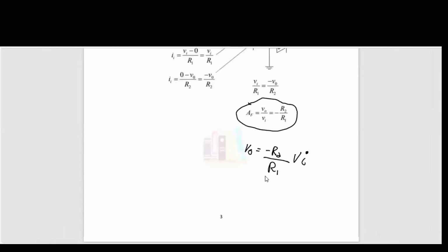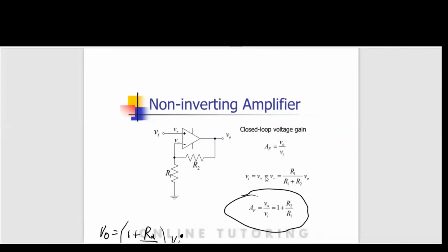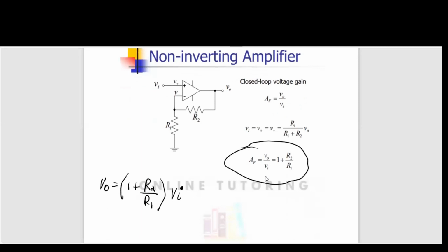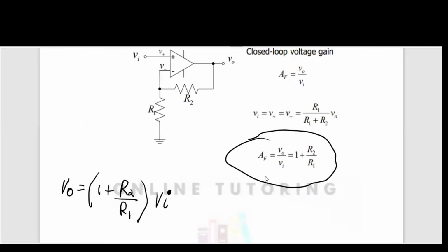Alright, so we're just going through. This one is literally just to sit down and remember the circuit. Alright, non-inverting amplifier. This should be familiar from physics. The equation for it is here, so you'll use this one. V out is equal to 1 plus R2 over R1, times VI. So you have to remember those equations. Once you remember the equations, guys, you could get all the marks for this section. And obviously, how to draw the circuit.